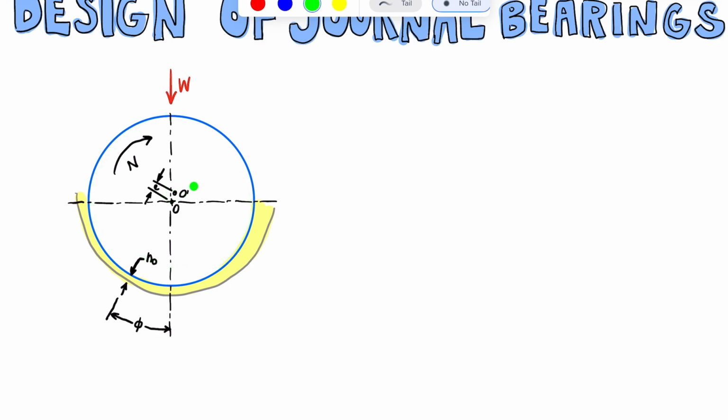So the shaft starts with its center cross-section at this O prime, and then after a load is applied, after we start rotating this thing, it's no longer concentric with the housing and it's moved to this new point O, and that distance from the original center to the new eccentric center is e. All right, so let's list out not all, but some of the independent variables and dependent variables that are part of this model.